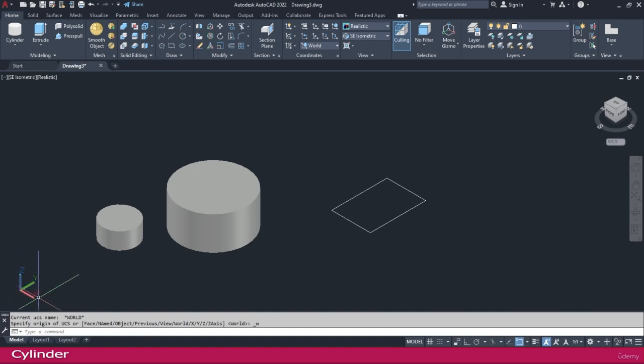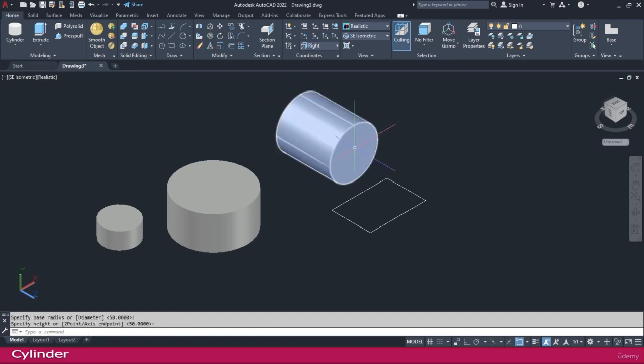In that situation, if you go here, you can see the right side. If you need to make any geometry or primitives, just set it to right side. Now it is ready. See here, X and Y are ready. Now I go to the cylinder and click the first center point, and now you can give the radius and the height.